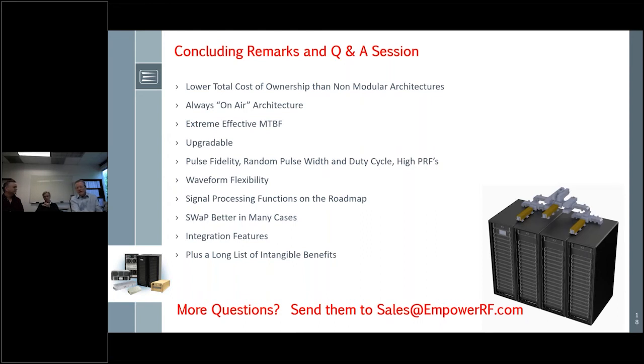I'd say, without speaking in absolutes, LDMOS for us is probably 1 gigahertz and below, and then gallium nitride on silicon carbide is device selection once we're above 1. And the work we're currently doing, I think George mentioned at the outset, we're going from HF to X-band with our portfolio.